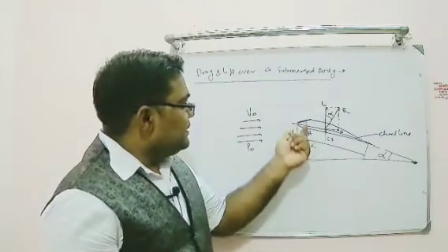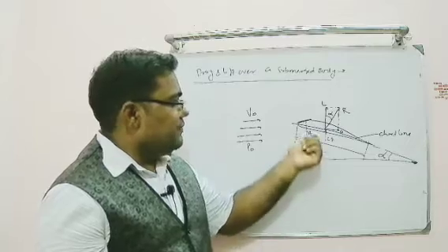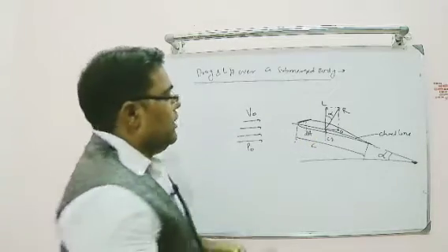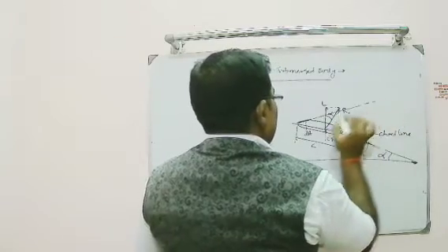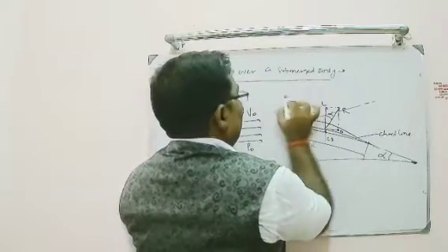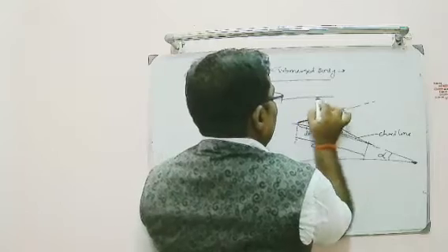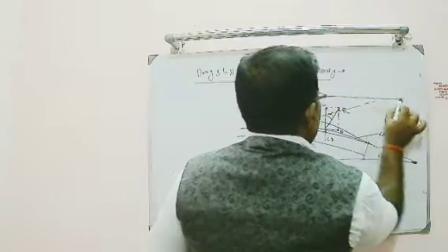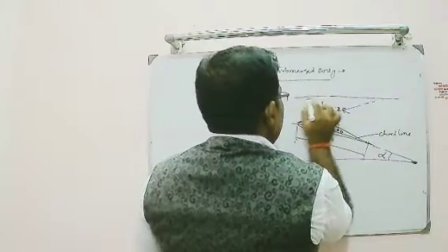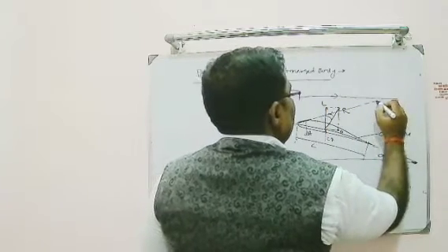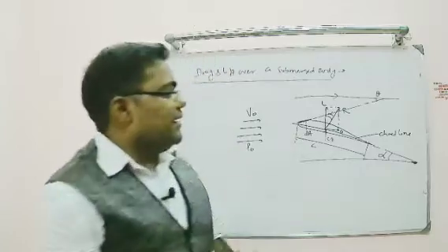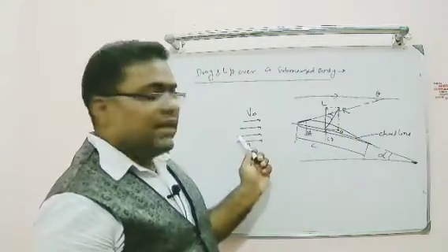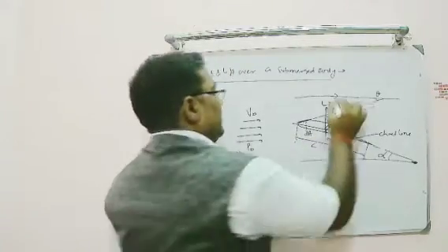So that's why I have considered one elemental strip here, which has area dA. If I extend this line like this, and draw the free stream flow direction, which is here horizontal, it's basically a horizontal line. This is the free stream flow direction. The striking point is the angle theta. It makes a deflection angle theta with the free stream flow direction, V infinity.